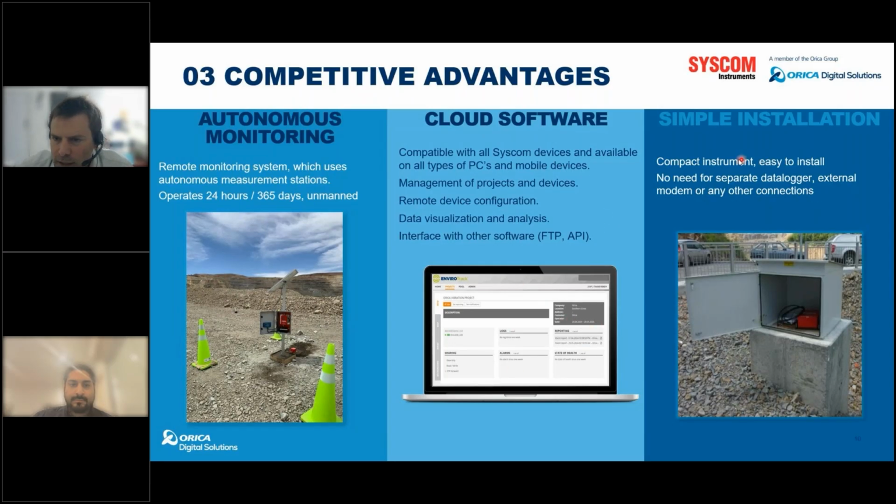And normally it's quite a simple installation: you just install a concrete pedestal on the mine. This is also what we see on the left. The idea is to have a proper coupling to the ground, which is key for transferring the ground movement to the sensor inside the red box here, and to have the same measurements basically of the ground's lateral and vertical movements.